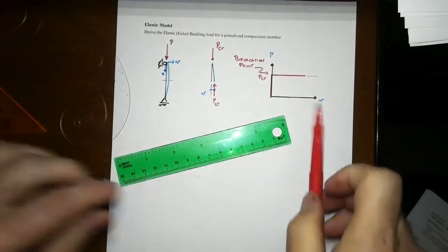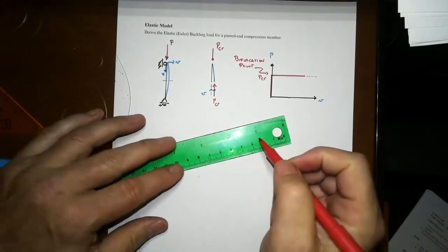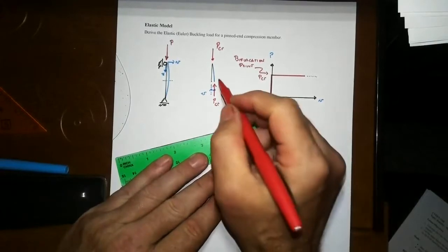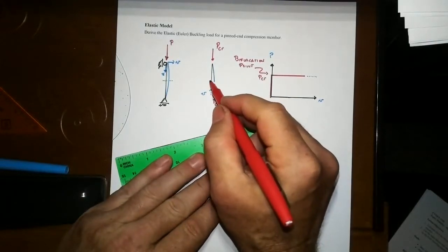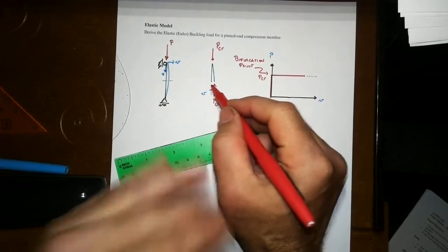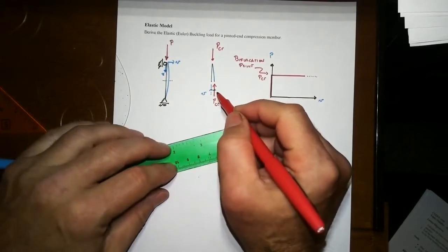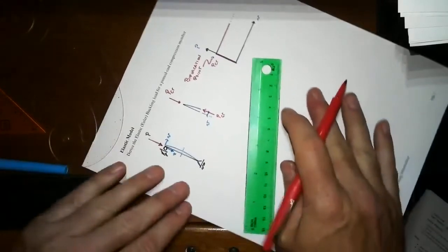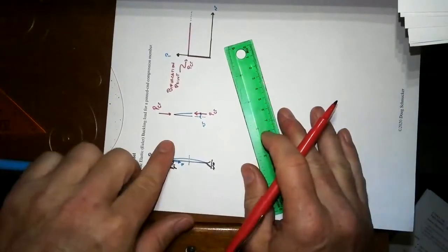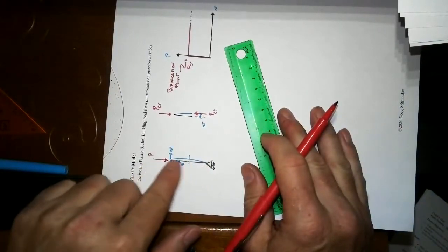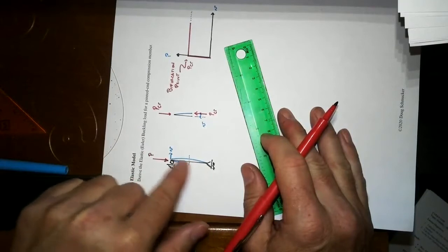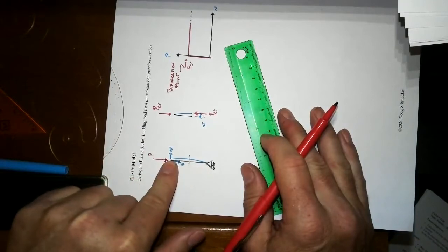Now the member is bent. Now this will seem a little weird here. The way the bending is, clearly the compression side is on the left, and so the actual physical moment is acting to the left. But when you regard that our sign convention is such that up is now positive, what you've got shown here is a frowny face or negative bending moment. That's a little weird.